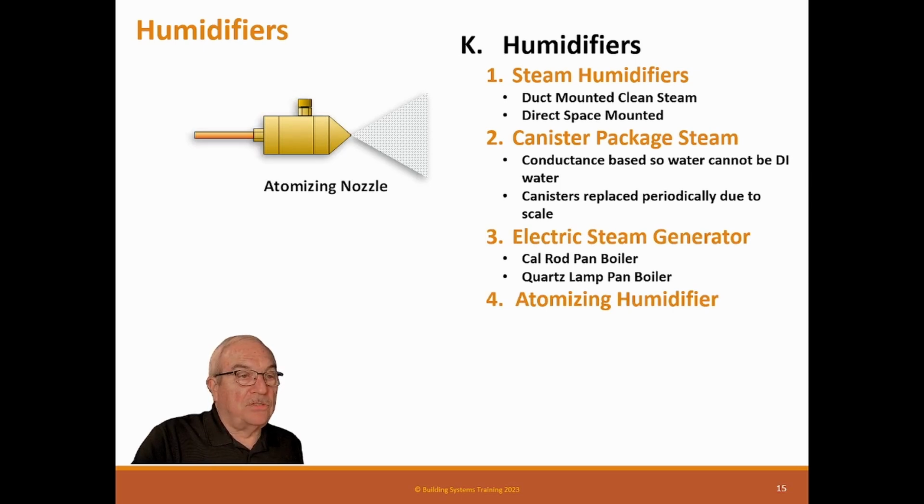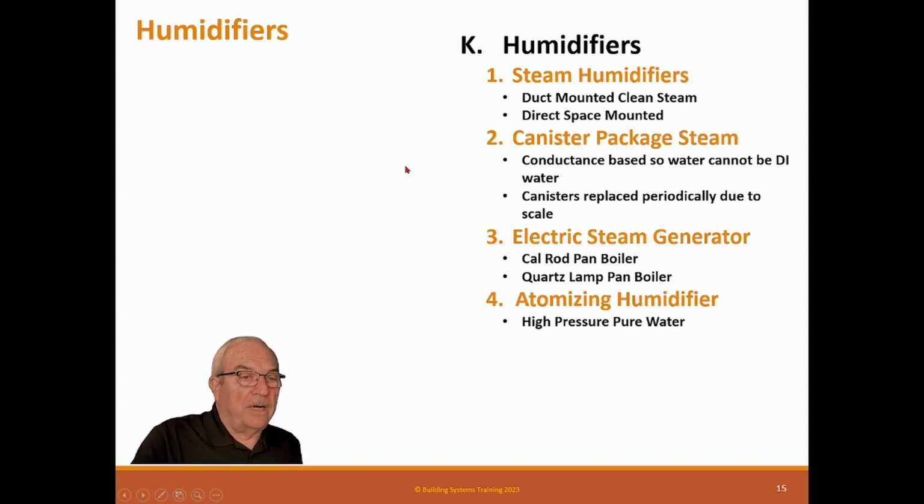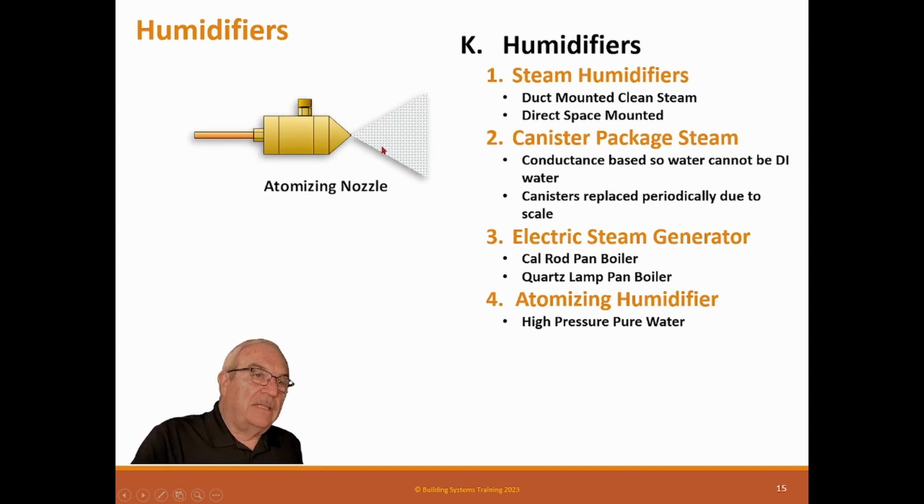Atomizing nozzle, which is just a fine nozzle, has to have real high pressure water, normally 300 to 600 psi. It has a special pump, of course, to do that, and it breaks the water into a real fine mist. We use these in my town to cool patios and things. The problem is that these should not have calcium in the water. If they do, this thing is so powerful that it breaks the calcium into the smallest final particles and can cause breathing issues. So this is a problem.